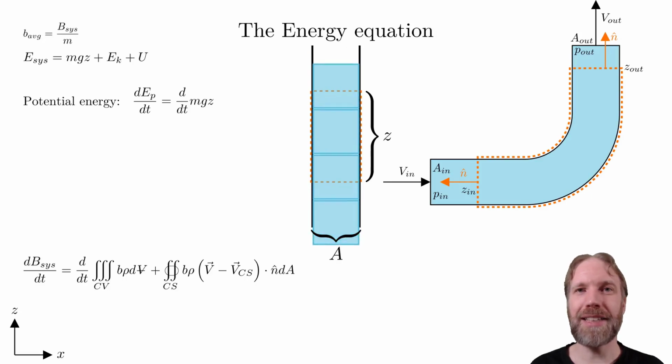We see that the height of the control volume is constant, but the mass particles move. Hence, when we work with control volumes, the time derivative will act on the mass, which will turn it into the mass flow. We call the dm/dt m dot. The mass flow can also be given in terms of the average velocity, the density, and the area.